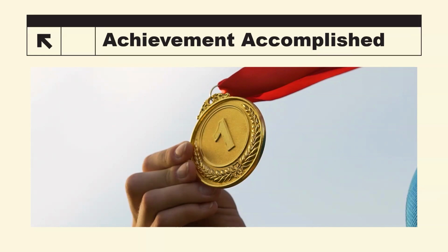They're doing it so that they're able to apply the grade 1, 2, and obviously hopefully not 3 to these different aspects of the system so that they can get additional points for things like Energy Star and so forth, right? And the problem when it gets to the refrigerant is that it's somewhat common that they basically just rely on the HVAC contractor to do the weigh-in method, but then they fail to do all the additional things.